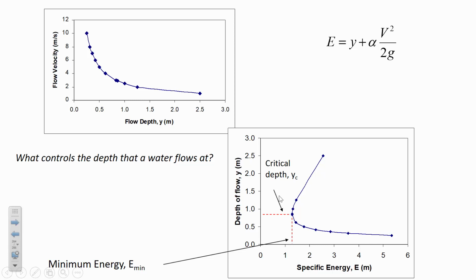Like if you take the trough that the water's flowing through and make it really steep, then it's going to be shallow as the water goes down that slope. So below this dividing line, below the critical depth, these are regions where the flow is supercritical. And above the line, that's called subcritical, where the flow is moving at a lower velocity.